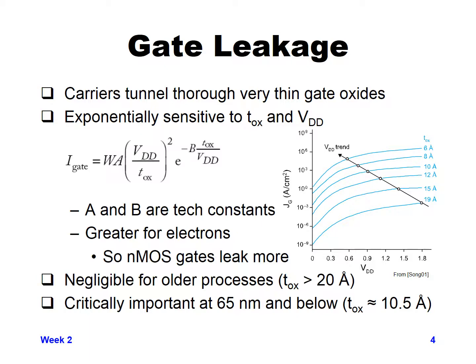You can see that as they've been decreasing the oxide thickness, they've also been decreasing the VDD, the voltage that you use. That does offset your leakage a little bit, but you can see that it has a very small effect overall. Maybe instead of 10 to the 6th leakage, you're maybe down to 10 to the 5. So it helped by about a factor of 10, but when you were going by 9 orders of magnitude, one factor of 10 is not enough to totally offset you.